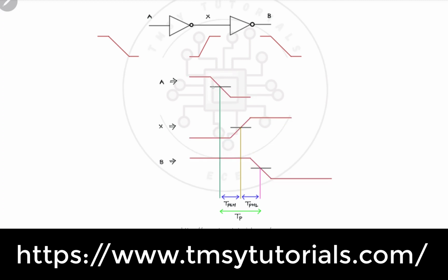Now I'm taking 50% as a point. So for A this is a 50% point, and for X this is a 50% point. Draw a vertical line here, and here, this is TP-LH. Why it is TP-LH is, here X is moving from low to high, so that's why TP-LH.